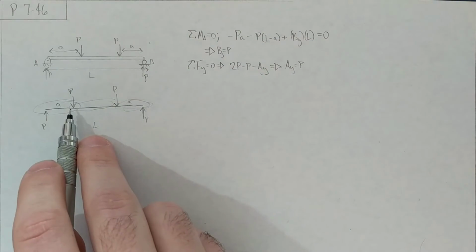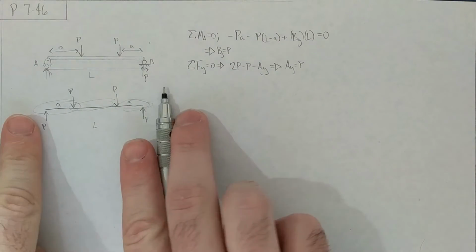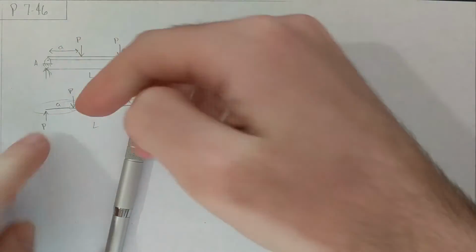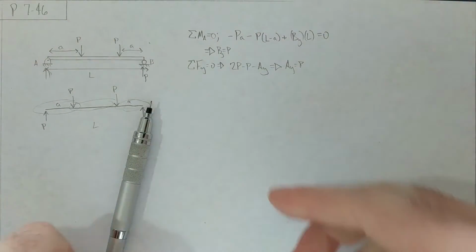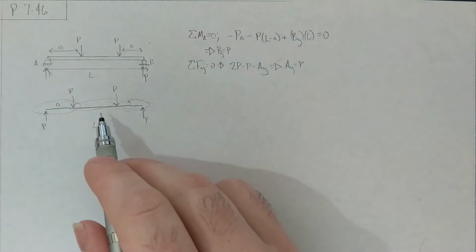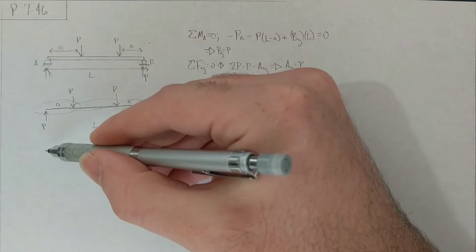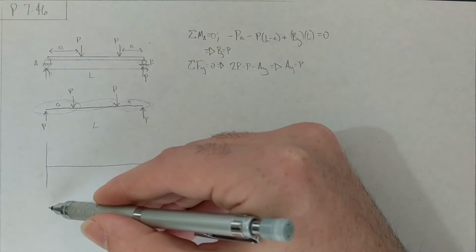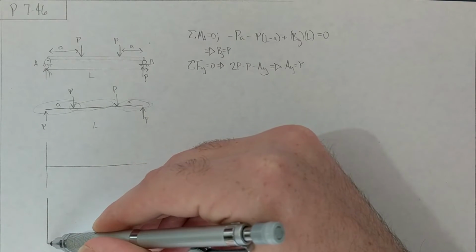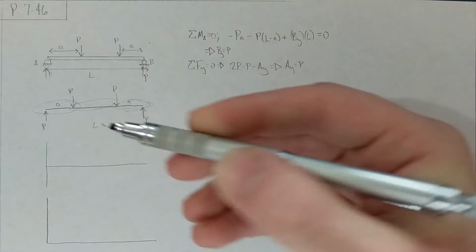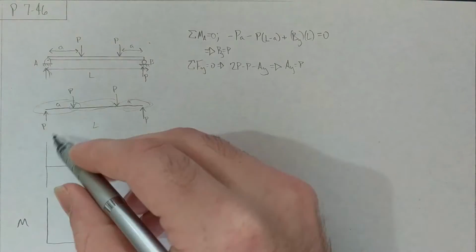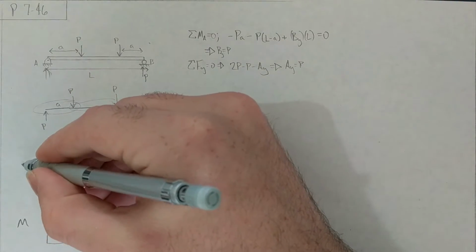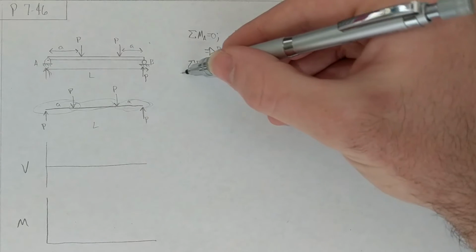As you can also see, with these point forces in the middle pushing down, it's going to be concave up, smiling. So you know that the moment diagram is going to be, so let me just draw the shear diagram. You don't have to draw these axes before you do your calculations, but we just know that moment's going to be all positive, and you can tell that shear is going to have some negative components too. But anyway, let's go figure that out.